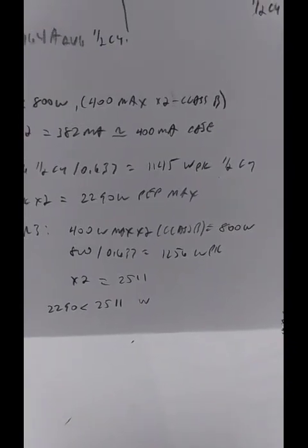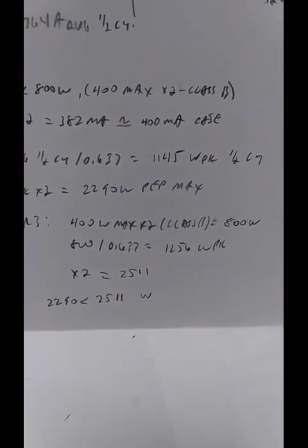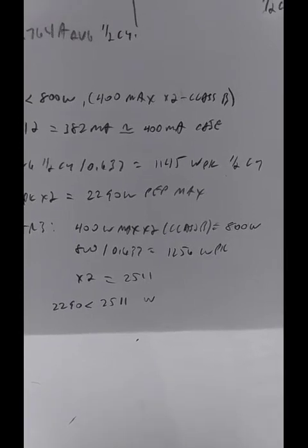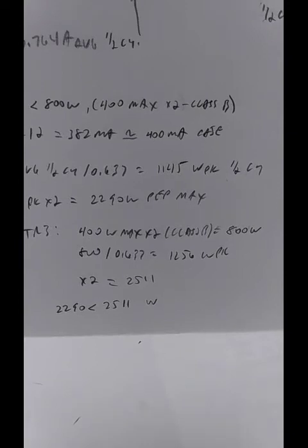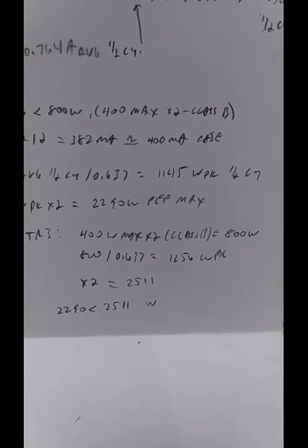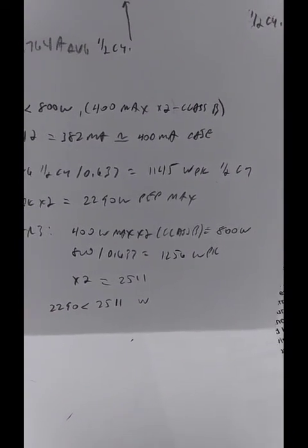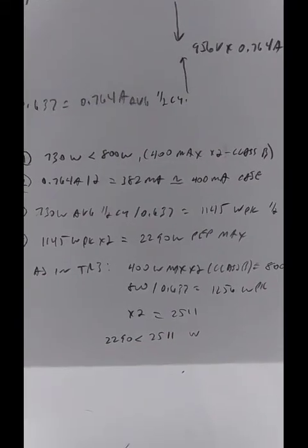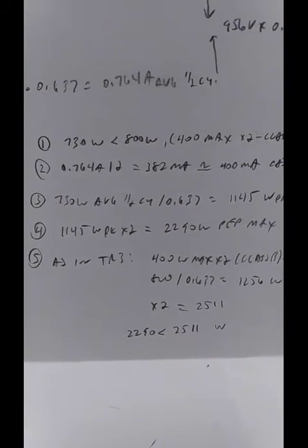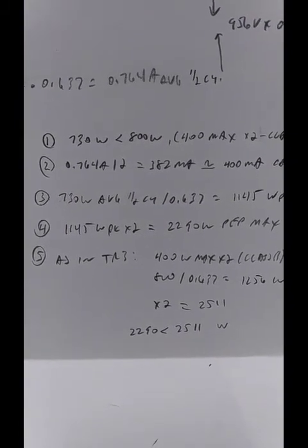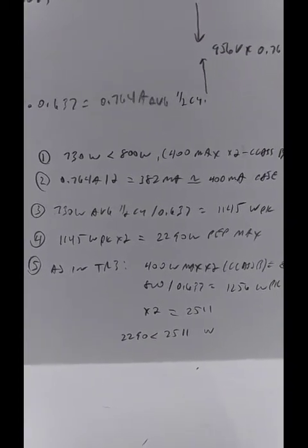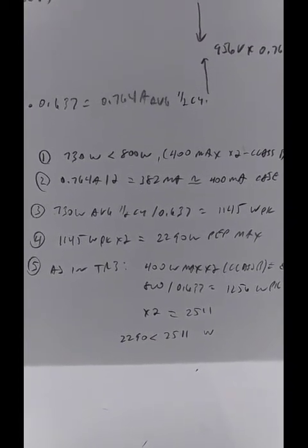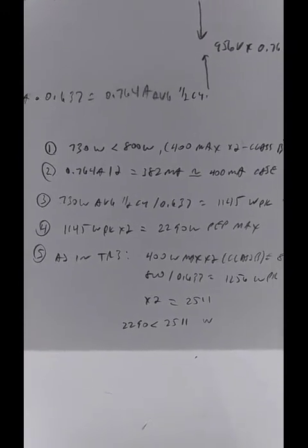The qualification here is that the case on the data sheet is working into a resistive load, and that goes someplace interesting here in a minute. Extremely confusing. So for a resistive load with the tube only conducting half cycle, then there's no flywheel or swing effect, and we don't get the number 4, the multiplied by 2. And if we work from there backwards up, we see it's still within limits for 400 watt tubes, so it's still legal.